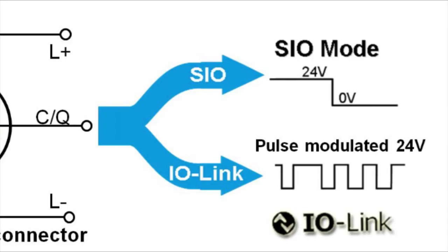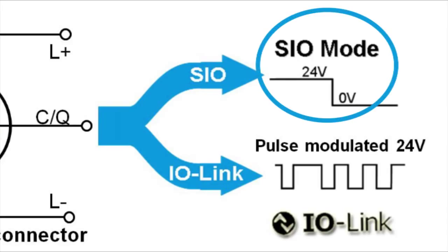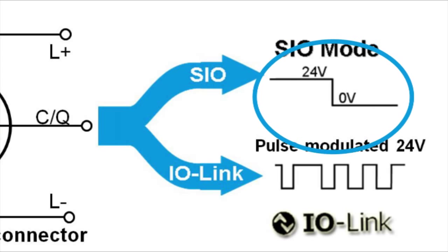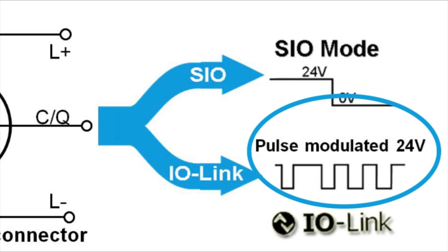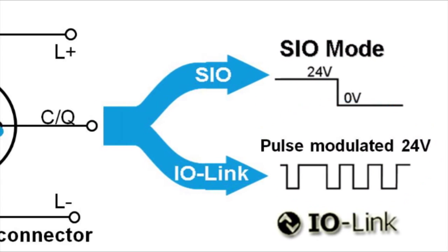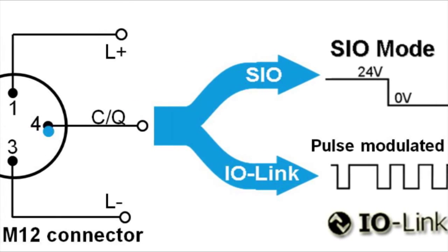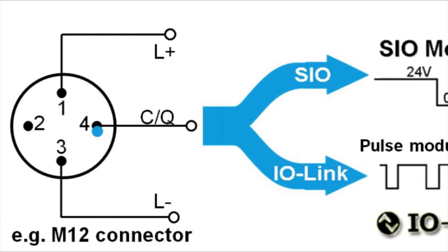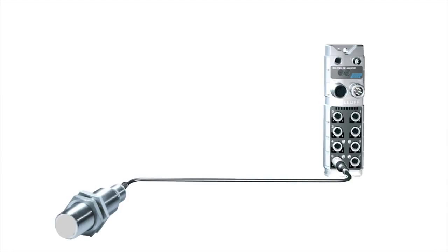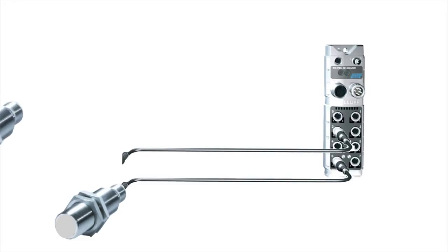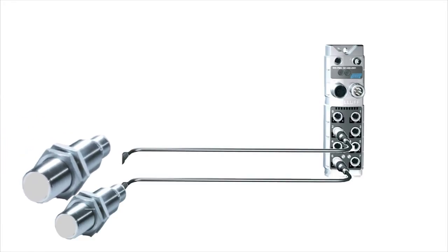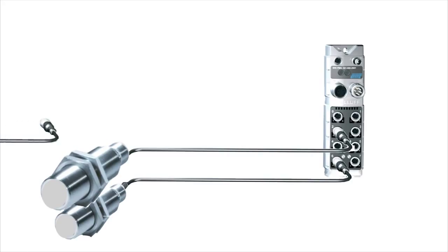IO-Link transfers the well-known signal technology of binary signal interface and, as an add-on, can transmit I/O data via serial protocol. It eliminates the bottleneck between the sensor and field bus level by making today's binary standard sensor interface capable to communicate. When defining IO-Link, for reasons of investment security, particular emphasis was placed from the very beginning on maintaining as much compatibility as possible with the existing technology.